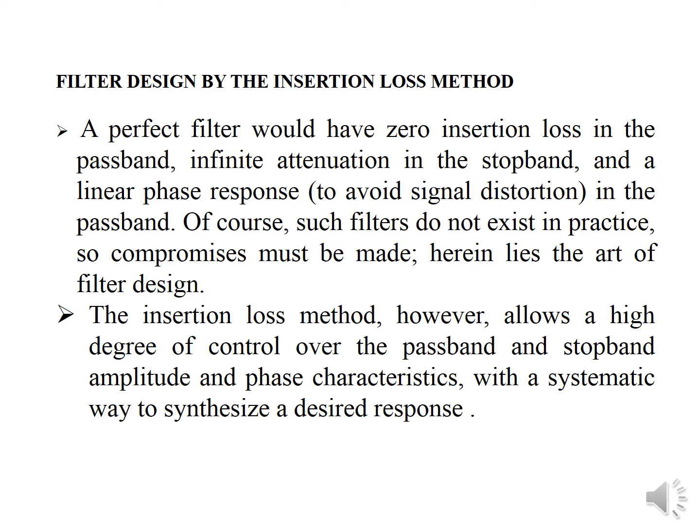Of course, such a filter does not exist in actual practice. So in order to compromise, we use filter design. By using the insertion loss method we can allow a high degree of control over the passband and stop band amplitude as well as the phase characteristics, with a systematic way to synthesize a desired response.